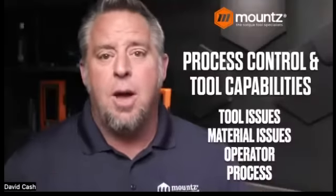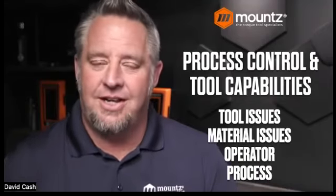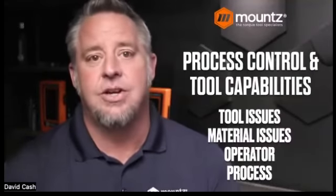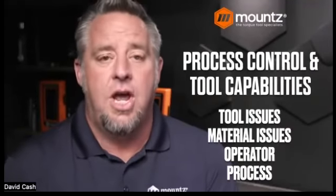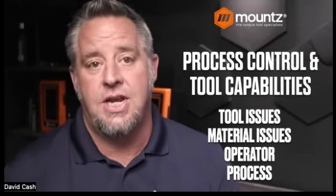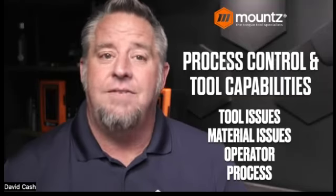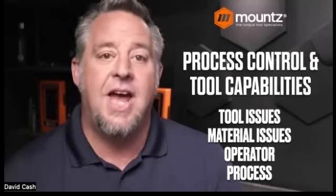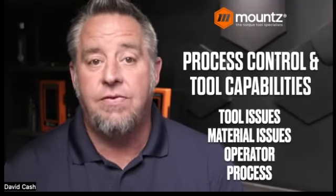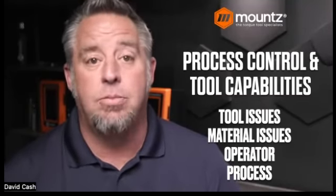With the CM and CMK testing, what this really does is allow you to focus on the process. If you are given the task of trying to improve a specific process and you're trying to measure what that is, the first thing you'd want to do is measure the tool that you would be using with your CM and CMK values. If you do see a CMK value that's under 1, you know that you can start with the tool itself. There may be some issues with that tool. It may need to be serviced. It may need to be recalibrated.